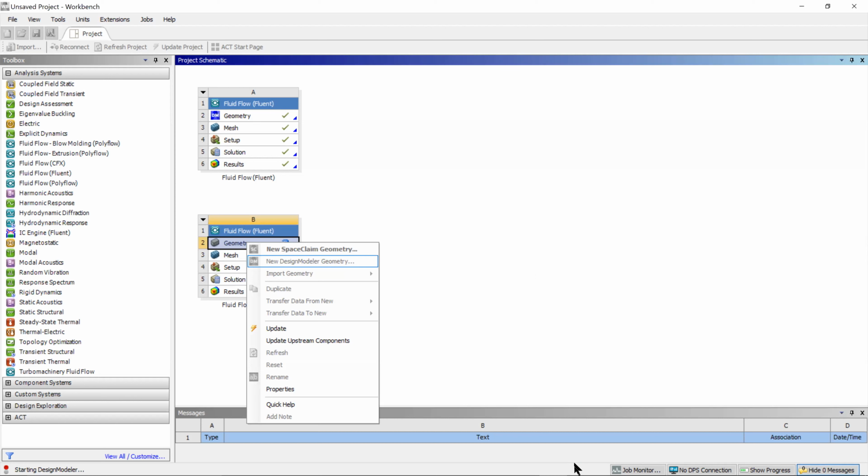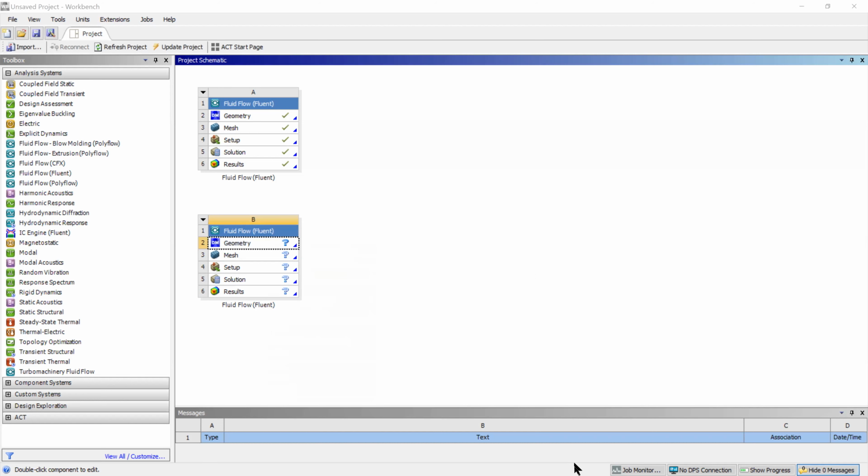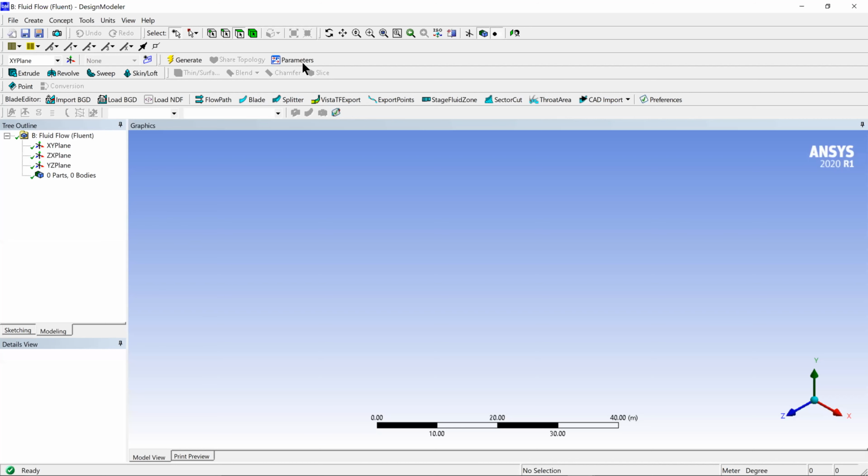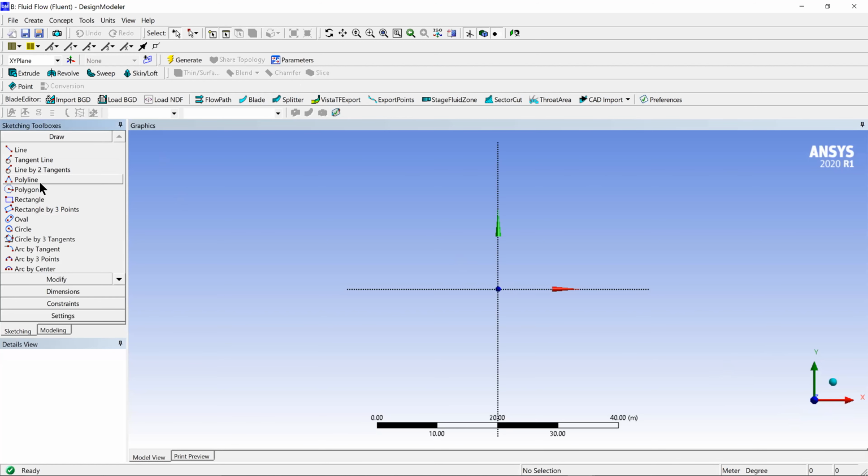Okay, so here we are. We're gonna select the Z axis point of view. Then we're gonna click sketch. And for this, we're gonna click rectangle since we're gonna do the plate. And we're gonna start from the origin to sketch.